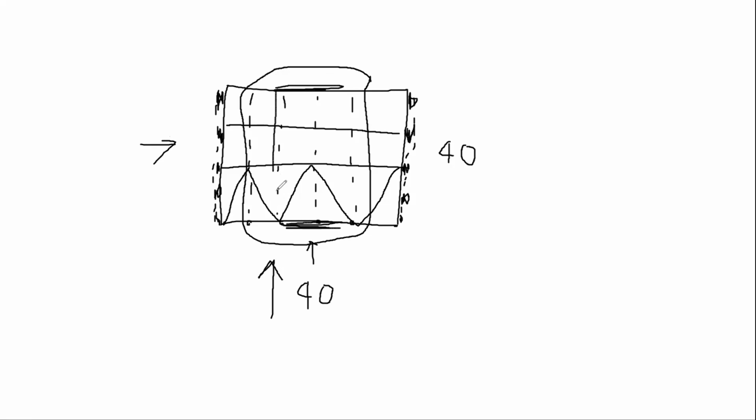Well, then we would have to create a diaphragm in the X direction. And so now all the forces can be transferred into the moment frames in the Y direction and the two shear walls in the X direction.